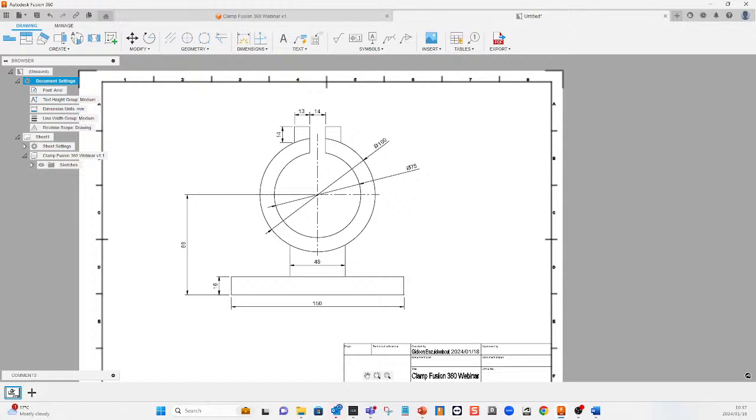Just to give a short rundown on the document settings, you go to the second tab, you get the annotations tab, you can open sketches and change the line types to continuous. Here you will be able to change a few features like your appearance, your colors of the lines, the selected line types. On the first tab, settings, customizations can be done on your text, your units, millimeter lines, widths, just to name a few. The third tab has visible outer lines, center marks, and bend centers for an example.